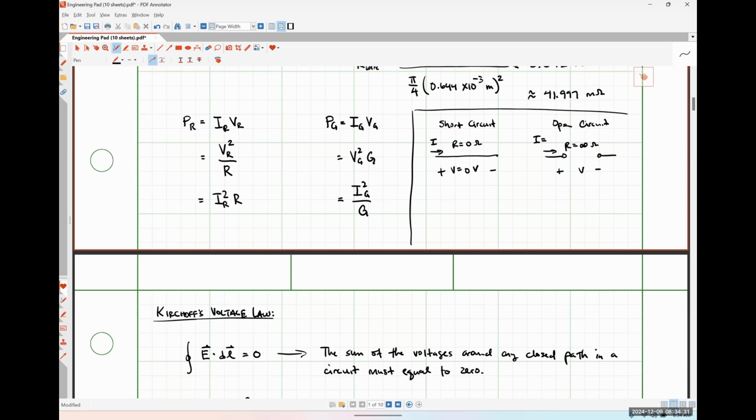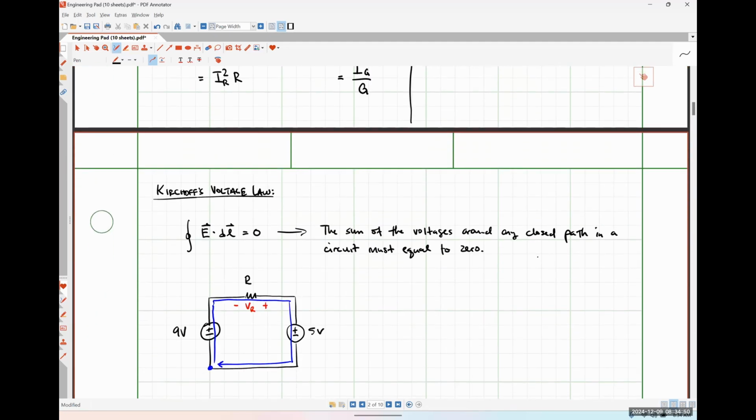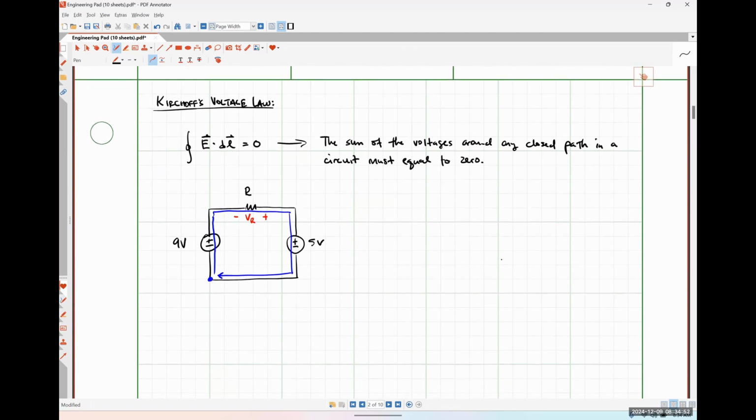We would have some voltage divided by infinity, which is going to look like 0 amps. So short circuits have no voltage drop, open circuits have no current flow, and it's because of the resistance that they represent. All right. Saying that now, we know what to do with the bottommost leg of this thing.